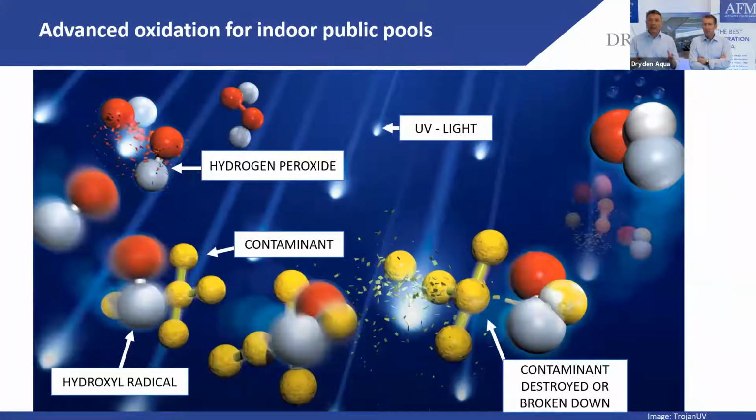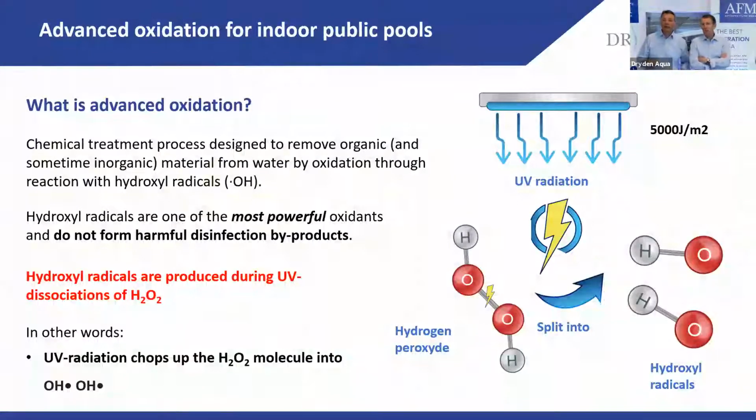It's the machine which will split the peroxide, H2O2, into hydroxyl radicals. And we have talked about this, the most powerful oxidants, short-lived, not like ozone. Ozone can survive minutes. Hydroxyl radicals, just a few seconds. So hydrogen peroxide is really the precursor in this case. You need the UV, and you need both. This is the energy that splits it.